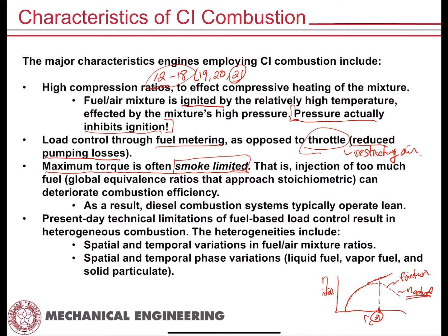But if you only had it marginally higher pressure, right? So say your air pressure is at 50 psi and you're injecting the fuel at 65 psi, well, that's only a 15 psi, only a 1 atmosphere pressure difference, right? So your garden hose, for example, has a larger pressure difference when you open the water spigot, the faucet, to spray water out of the garden hose, right?